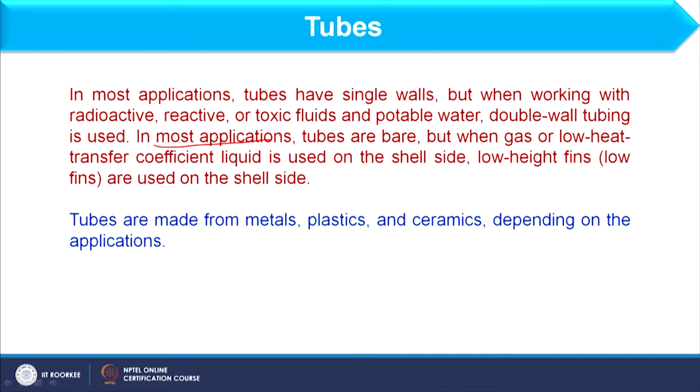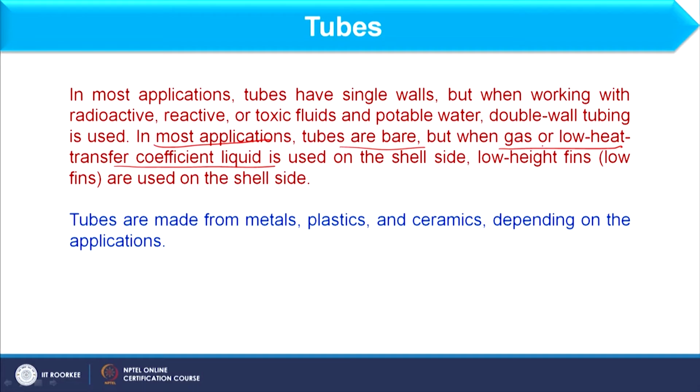And in most of the applications tubes are bare, it means we use tubes as they are, which do not have any other design over them. However, in some applications like extended surfaces, when we are dealing with gas or low heat transfer coefficient liquid on the shell side, we should use low height fins, which are basically attached over the tube. So these are basically tubes with fins, okay.